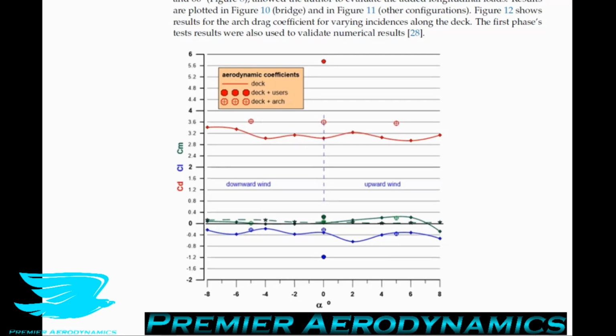So what would be the reason for such a high drag coefficient? I think the major reason is that there is just so much mesh, and that's because each wire has its own drag, but it also creates a back pressure and local boundary layers that significantly slow the flow in between these mesh parts. So effectively, even though you have such a small cross-sectional area, you have an artificially higher cross-sectional area because of all these boundary layers being formed and all this blockage that's happening.